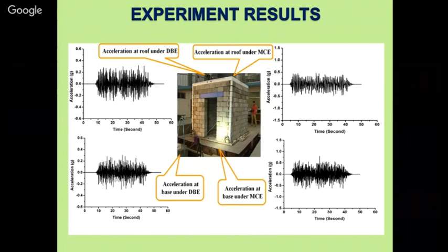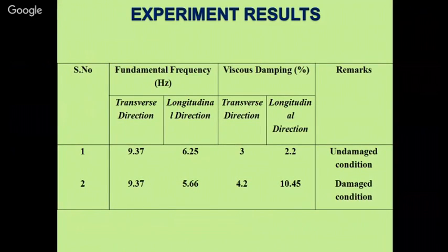In the first case, you have seen the uplift of the roof. That's why we made the 2-story building, because we want to see what the effect on the technology will be if the weight of the building increases. So here you can see that we have calculated the fundamental frequency and damping for the structure, in the transverse direction and the longitudinal direction. We have calculated the fundamental frequencies in both directions.